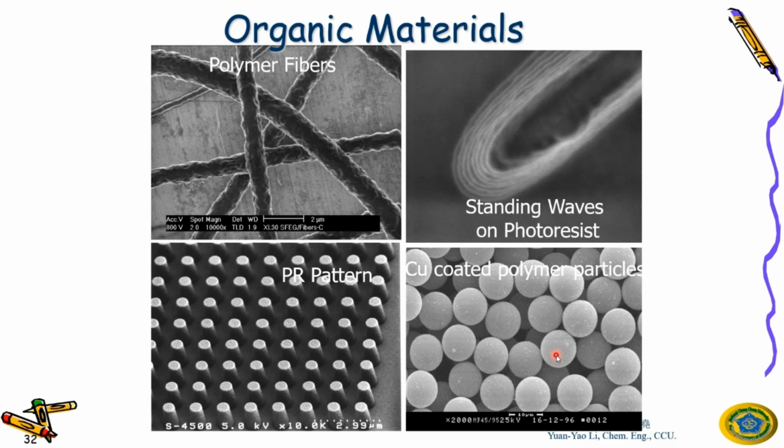First of all, take a look at the scale bar. Where is the scale bar? From here to here is 10 micrometer. So the size of this copper sphere is what? The copper sphere is about 10 micrometer in diameter. Right? Okay? And what's the magnification? The magnification here is X 2000. This is magnification in large.